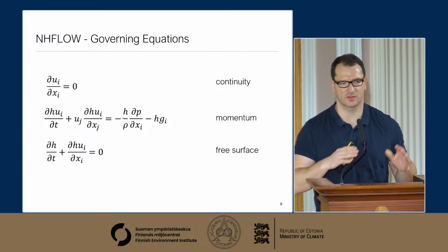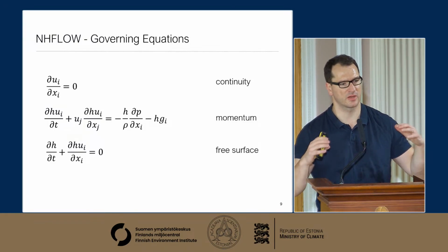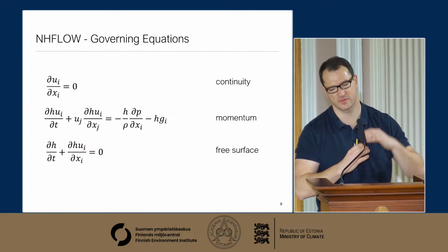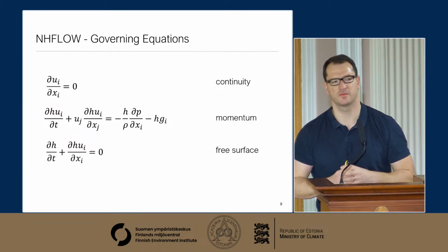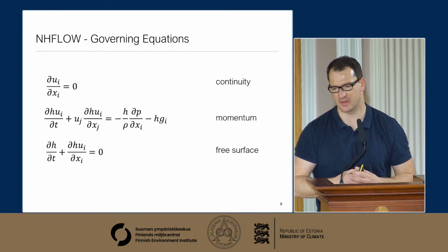And this is maybe in contrast to what we can do with the high-resolution CFD model, where we can look at two phases. We can look at the overturning crest of a breaking wave. With this type of model, that is not being directly captured, but we can represent the kinematics of a breaking wave.